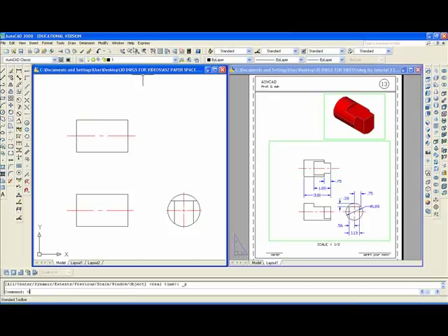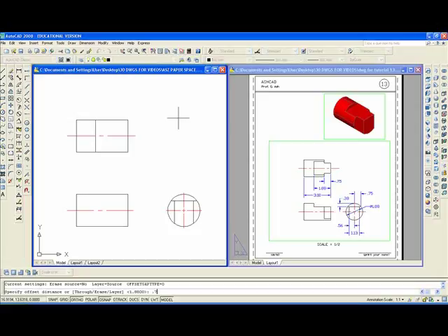To continue, we're going to type O enter, 1.88 enter, and move this line back. Then we're going to enter twice to offset 0.75, enter, and move this line back. Then we're going to offset again. Enter twice. 0.75. 0.75. Enter. And move that up and that down. And we'll offset one more time. 0.56. Enter. That line there. Oh, enter. 0.56.